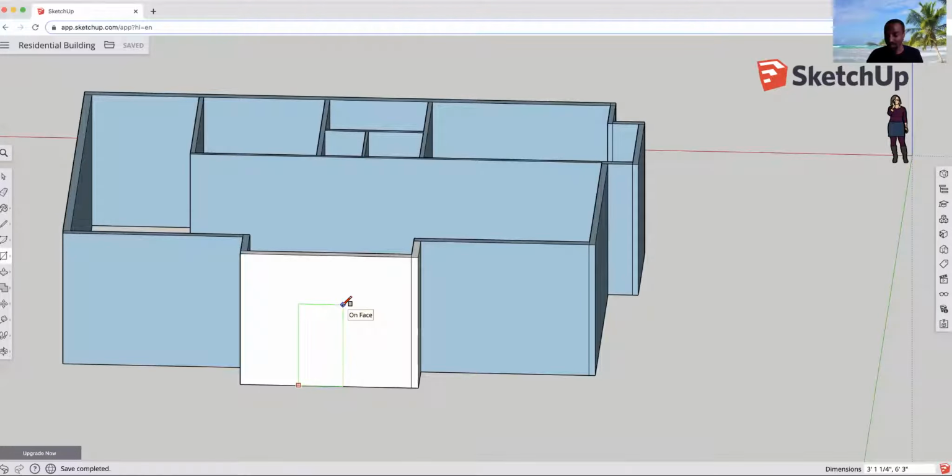The first set of numbers represents the width of the door, basically the door opening, how wide is the door. And then the other set of numbers represents the height of the door. So if I want this doorway to be 3 feet, I type in 3 feet, comma, and what's the height of the door? 7 feet, enter. And it creates the rectangle for the door, all right?